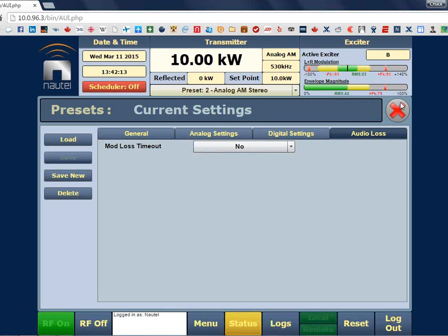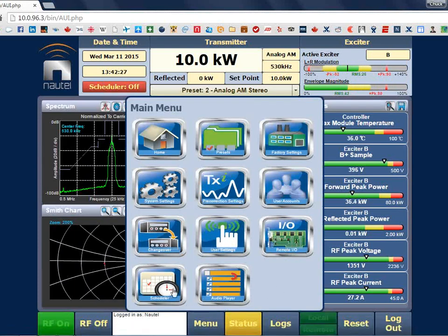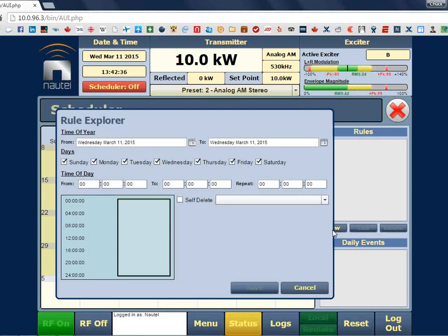Yeah. If you're a station that needs to go from a high power level to a lower power level at night, or even lower power level pre-sunrise, that can all be accommodated in the presets. And then you ask, well, how do I set that up on a timer? This is where you'd set up the scheduler. So you'd schedule automatically changing a playlist at a particular time, and you can go ahead and program an entire year off of your license. It typically will tell you what the time of day that you have to go from one power level to another power level in each individual month, because it changes on when the sun comes up, right? So you can program all of that in ahead of time and just be done with it.